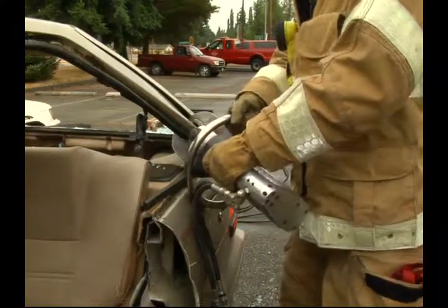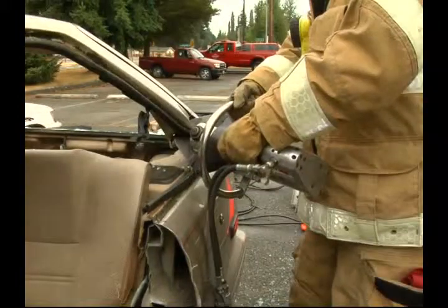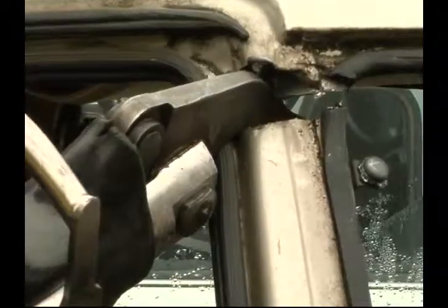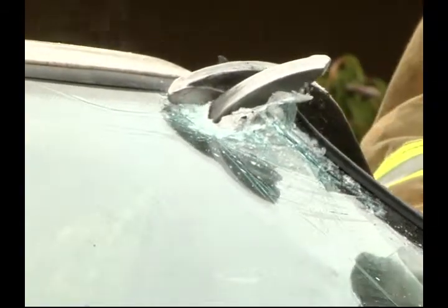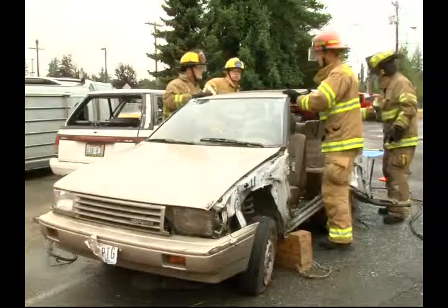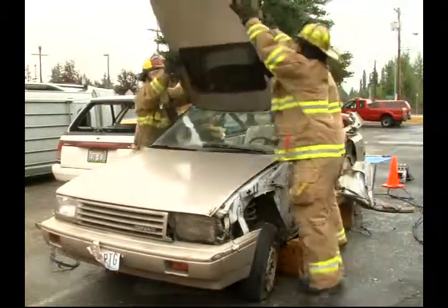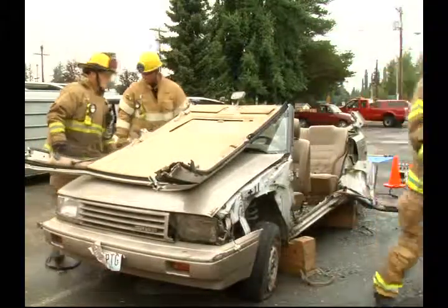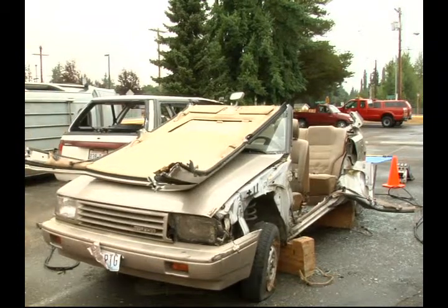If you are using hydraulic cutters, completely sever both the C or D posts near the bottom. If cylinders are present, cut below them to sever the pillars. Then, attack both B pillars near the roof line. Make relief cuts in the A pillars at the visors near the top of the windshield. Finally, flip the entire roof forward onto the hood of the vehicle. This technique is still an alternative if you need to gain access at the rear of the vehicle. However, materials used in new vehicles may prevent folding the roof, eliminating this option at some collisions.